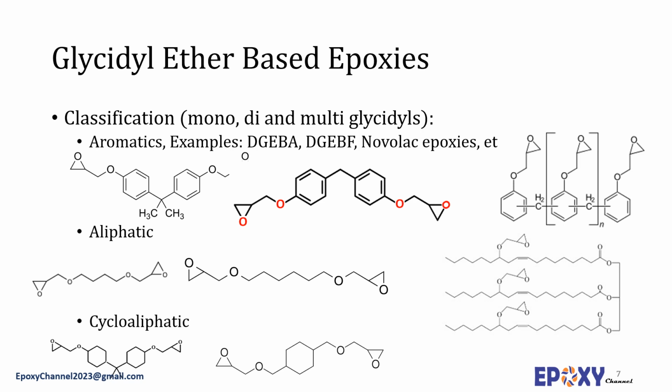To this end, two things should be noticed. Firstly, there are systems with one epoxide ring, often with much lower viscosities, which are used as diluents to reduce the viscosity of epoxy resins and simply other types of epoxies. And secondly, the choice of the reactive diluent for an epoxy system is dependent on the chemical structures of the diluent and the main epoxy. Therefore, aromatic diluents are suitable for aromatic epoxies.